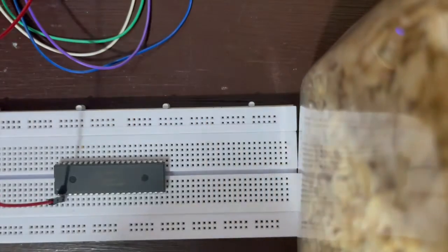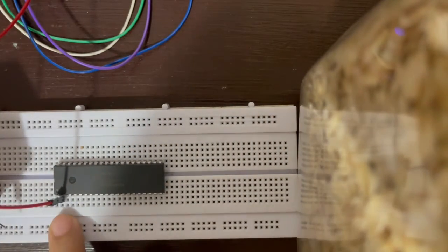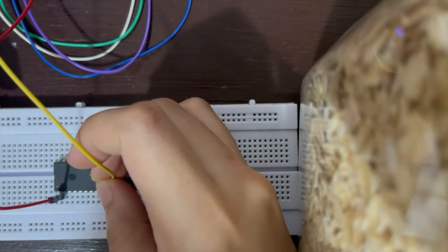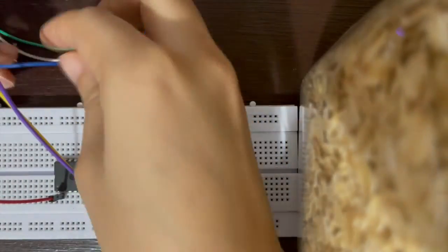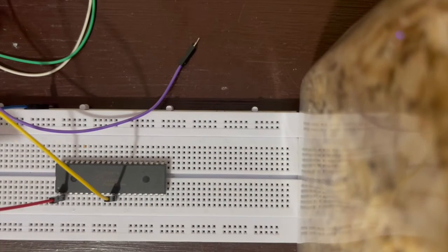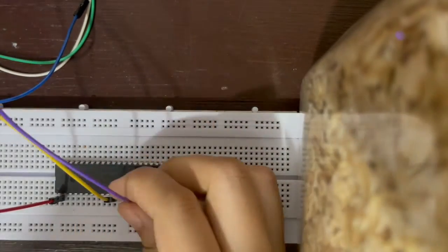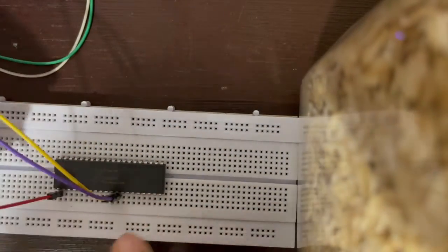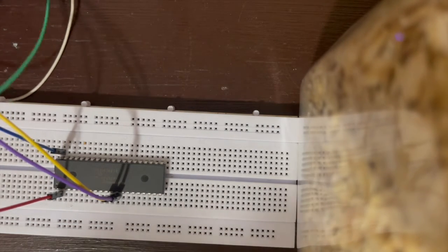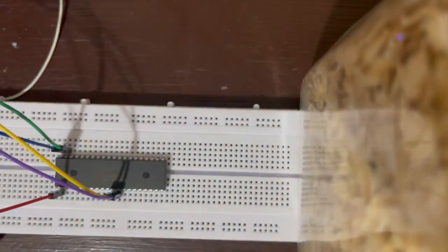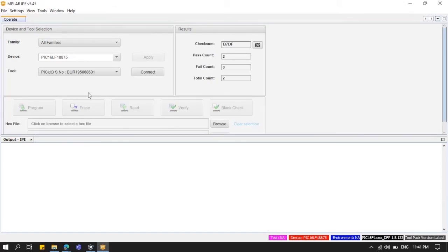We can now transfer that to the IC using the PICkit and using the connection that we used earlier. So it's the same. We're going to use the pin connection that we used earlier for us to transfer the 2-second code to the IC using the PICkit. The same procedure as in part 1 of the experiment.